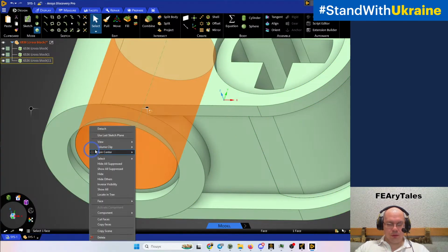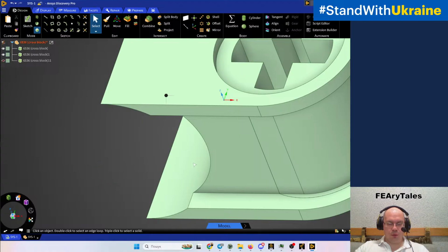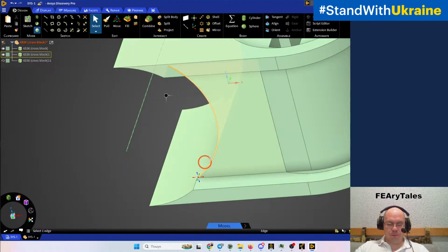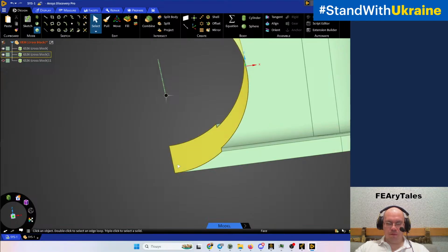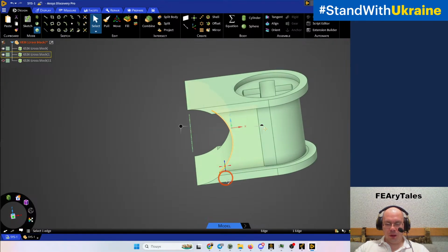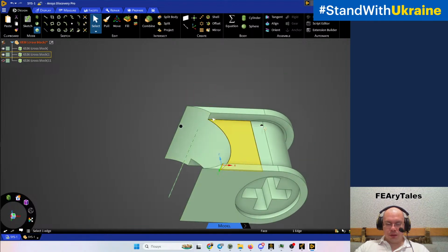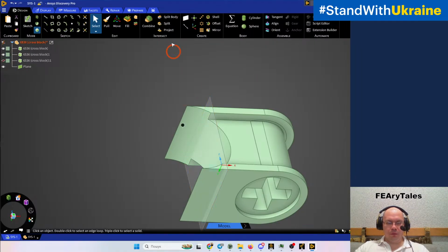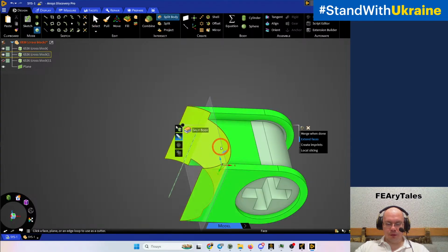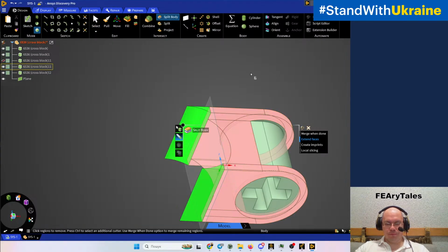And the third thing which I want to do, if we leave this object, we will obtain the very bad mesh here, so it's not a good solution. So we need to create an additional plane. We need to split those objects with those plane.